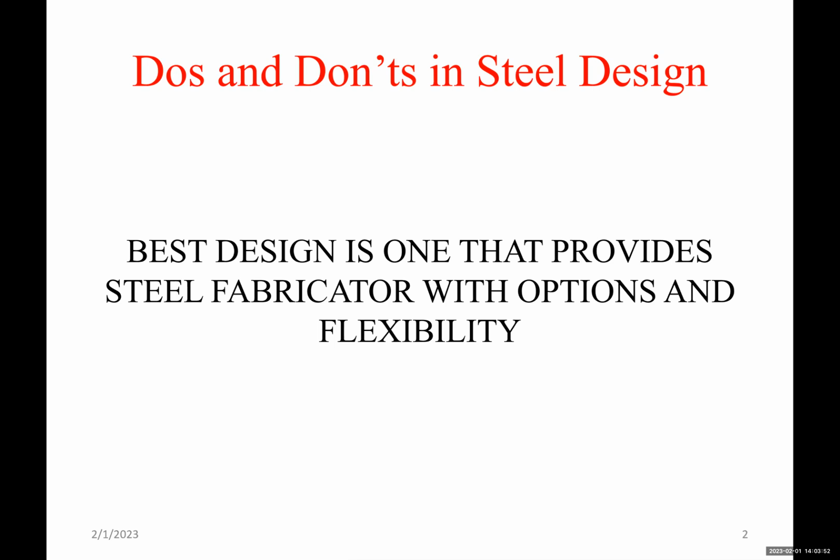So we'll think of different types of connections. And of course, the detailing of each connection may require certain things that are different from other connections. So do we need stiffeners? We don't need stiffeners. Is it a bolted connection? Is it a welded connection? So we have many options to do that.